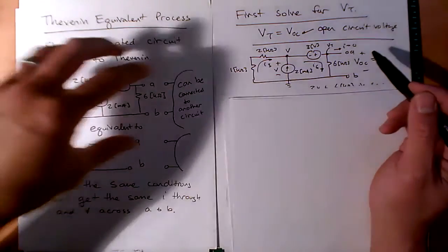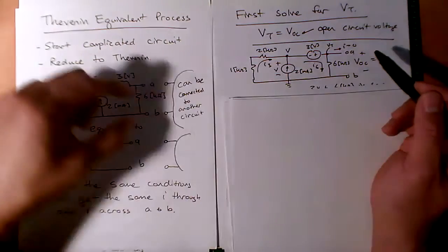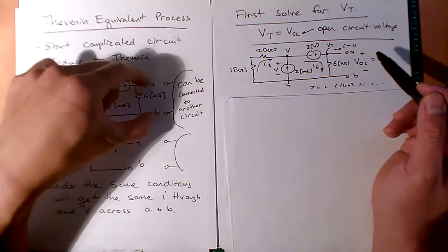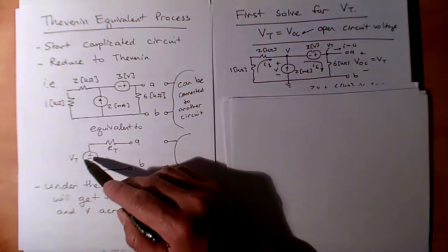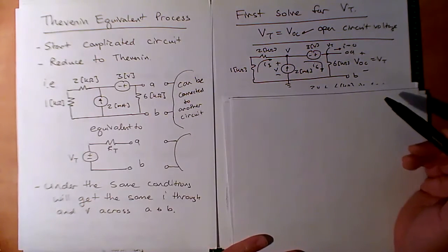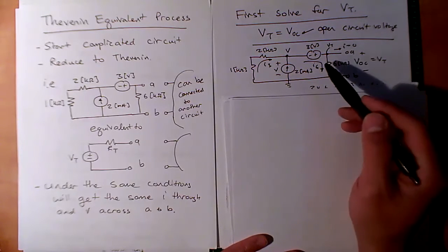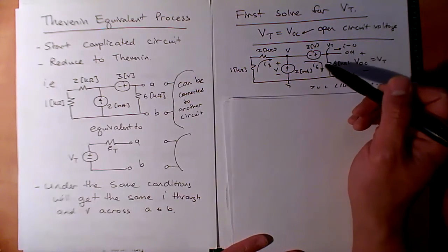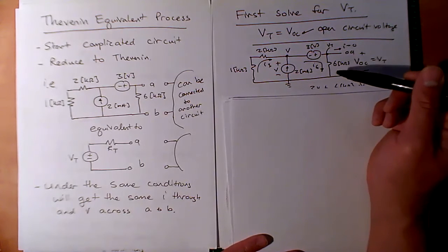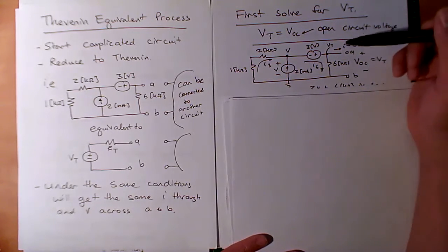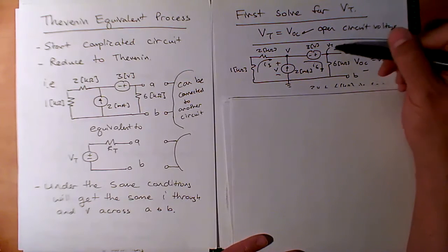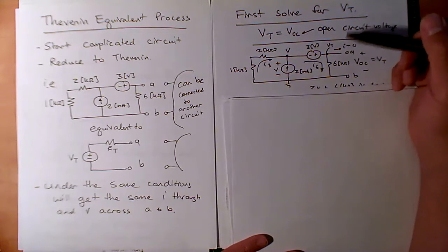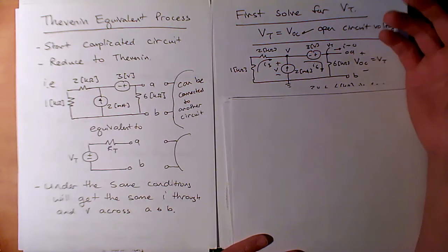So what I'll do, I'll disconnect it from anything else. I'll look at these two terminals and analyze this voltage here in the open circuit condition to solve for that value, okay, that equivalent Thevenin voltage. Okay, so let's go and we can now, at this point, it's an ET250 problem, and we can chip away at it, and we can see how do we get this voltage. All right, so some things to note. If this is open circuit, we know there's no current, so we can immediately assume that this current here is 0. Another thing I've done, just as a little trick, you don't have to do this because you can go other ways, but you might want to apply nodal analysis.